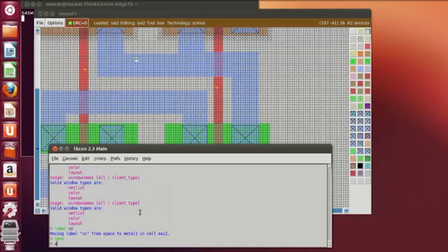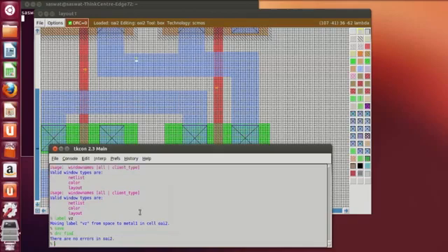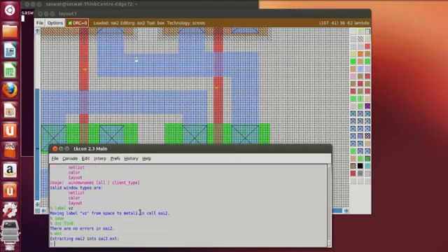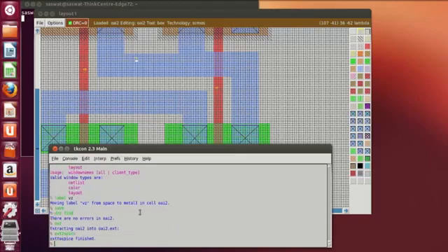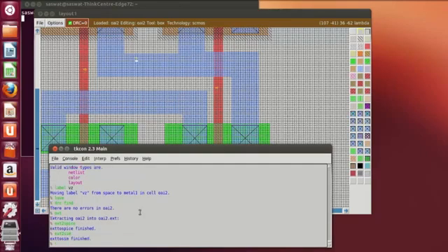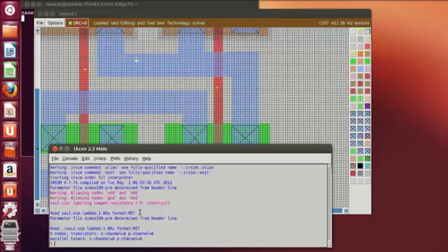After saving, find the DRC errors, if any. No errors. Then extract it. Extract to spice. Spice file extracted. Then extract to sim. The sim file is needed for the IRSIM. After extracting the sim file, type irsim OAI2.sim. Then you have to keep a watch on VA, VB, VC and VZ.